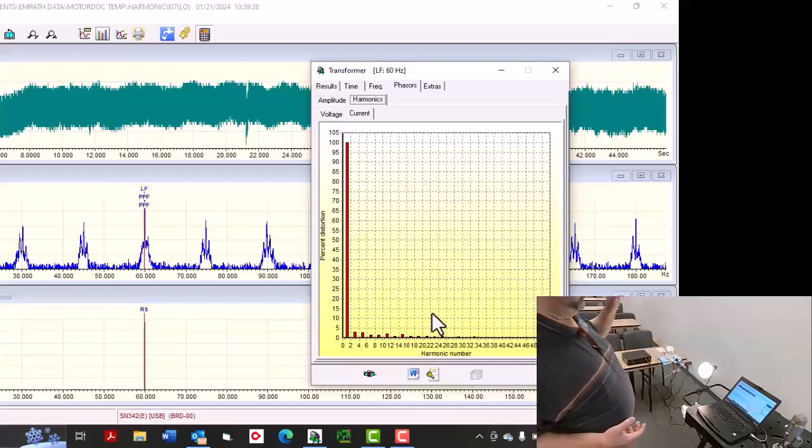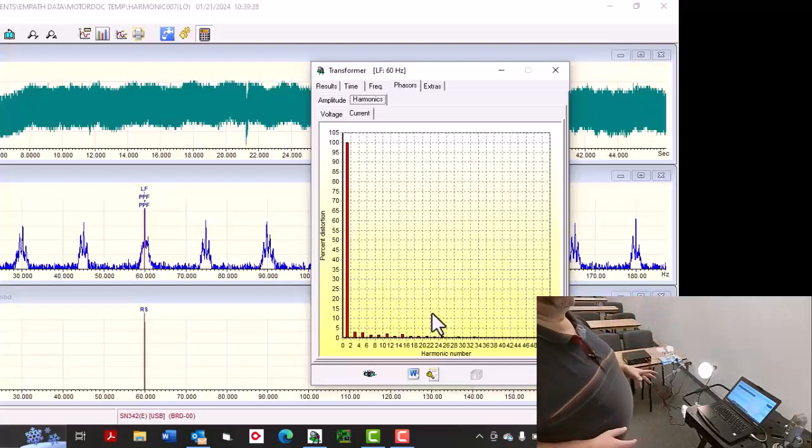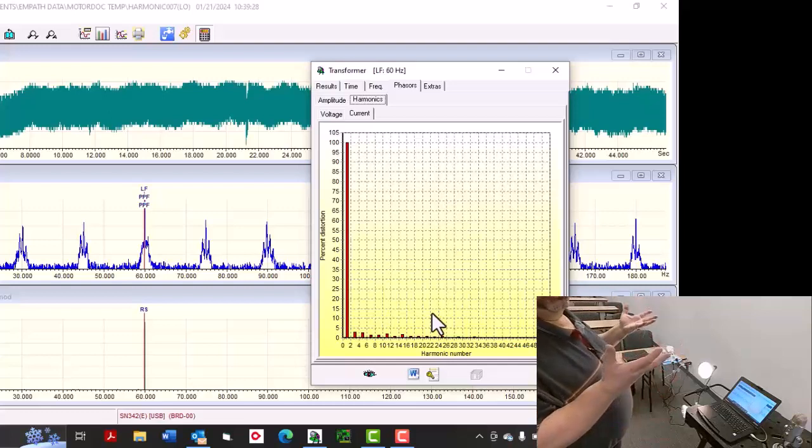Okay? So we often see that in surveys where somebody will go in, they'll say, oh, you're going to save energy, da-da-da. Here you go. Oh, you don't need to filter anything. We're just going to put this in. We're going to run it. And look, right at the circuit that feeds that lighting system or whatever, we're not seeing a change. But you go back further to a panel that's feeding a group of these systems, then you see the harmonics come up.